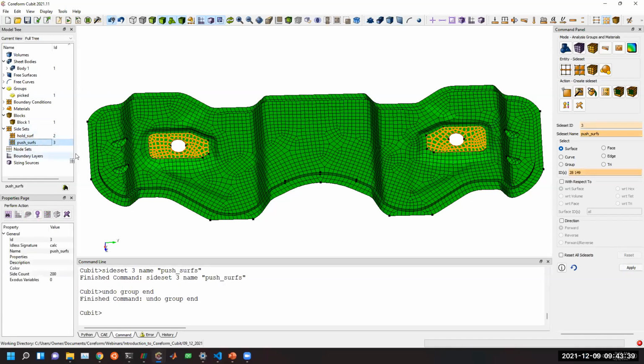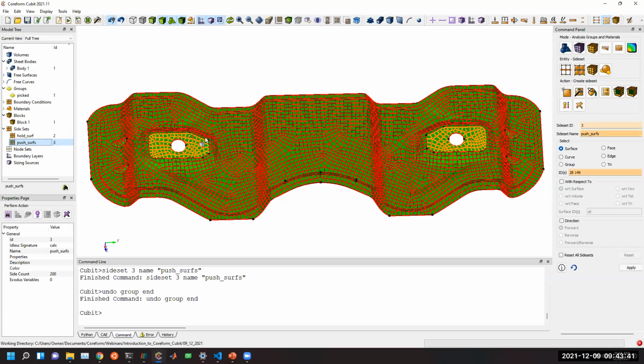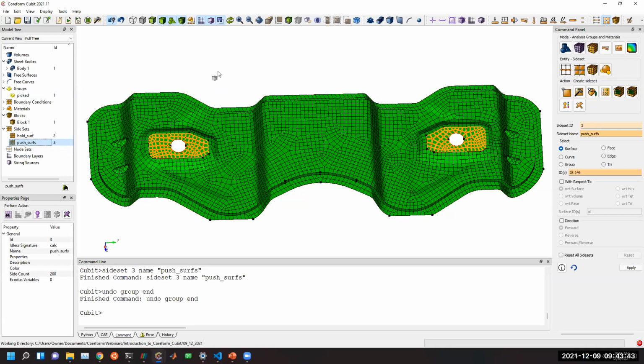So now when we build our U-spline, it's important you do this before you build your U-spline so that our U-spline algorithm will capture that topology and can then export it as BEXT. So make sure you assign your boundary conditions before you create your U-spline.